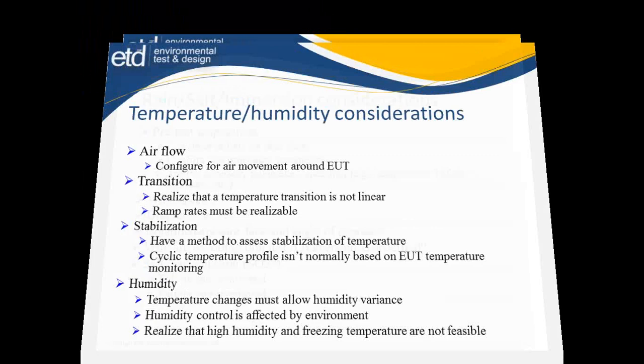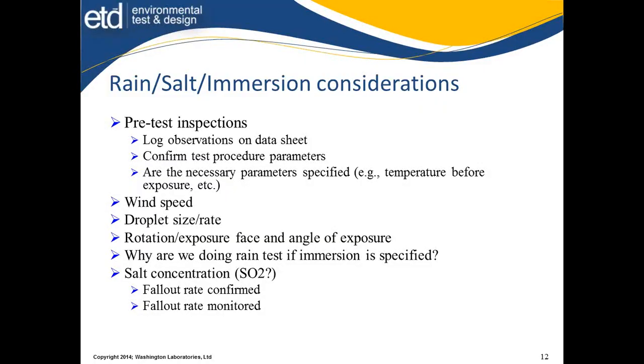And by the way, why are we doing a rain test if immersion test is specified? In our case, it was. Usually if immersion is specified, the rain test requirement kind of disappears because I'm going to put it to a worst case event by immersing it. But quite honestly, both tests are called out frequently. So be aware that just because it doesn't make any sense doesn't mean it isn't required.